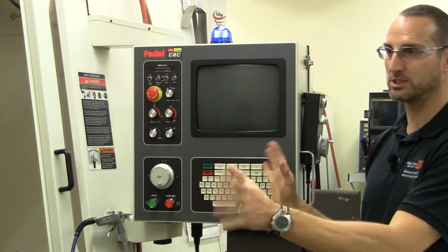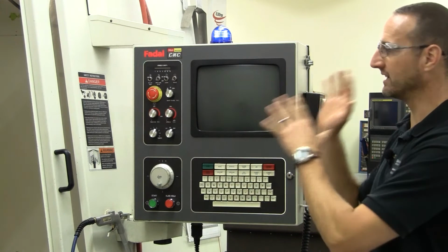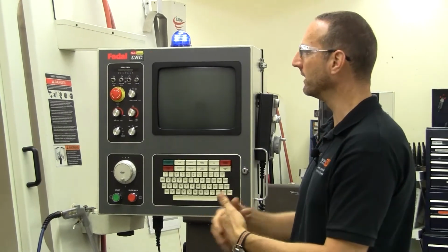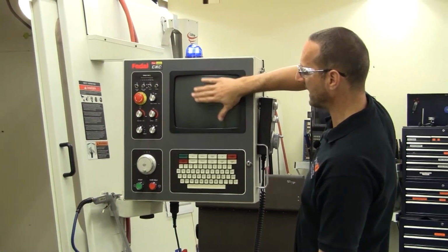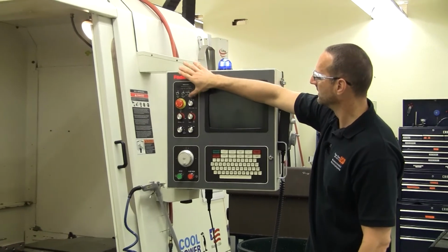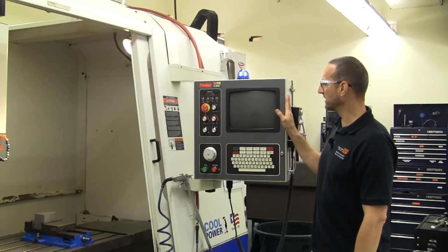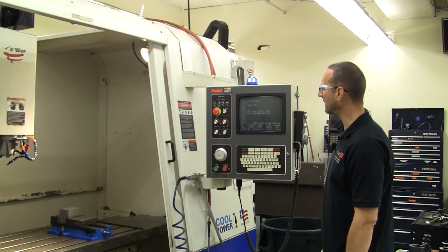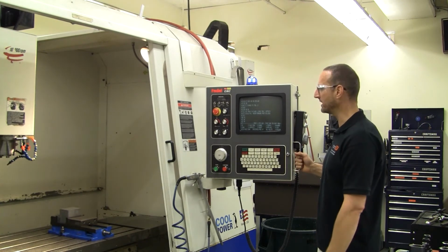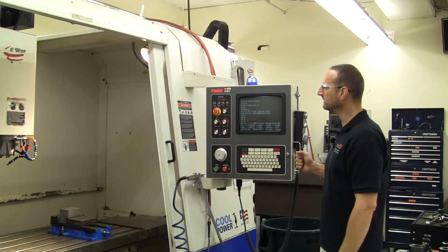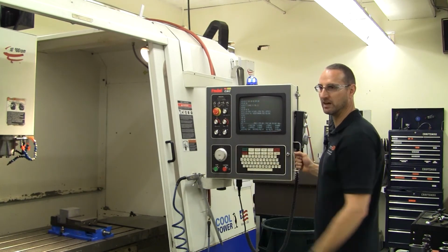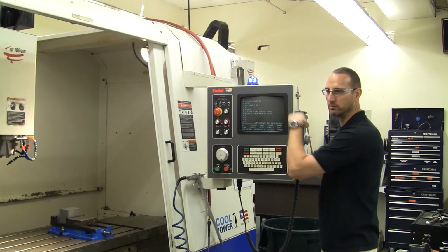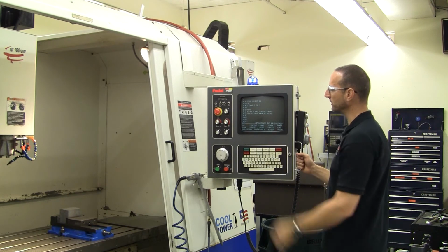Now recognize that does not shut down the controller. The machine is still on, the controller is still active, and if I was running a program, the machine would continue to run that program. All it does is basically save life on the CRT monitor. These are controllers from an older age, and there's limited life on the display. So often in a high manufacturing environment where they might be running 24/7, there's no reason to have the display showing stuff if there's not an operator standing there to see it. So that is why that was there, so you could flip that off and save life on your screen.